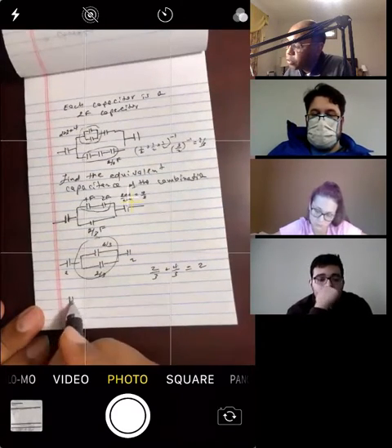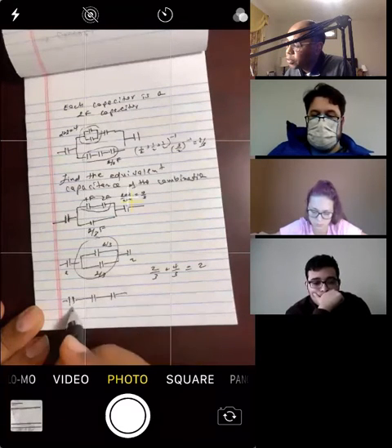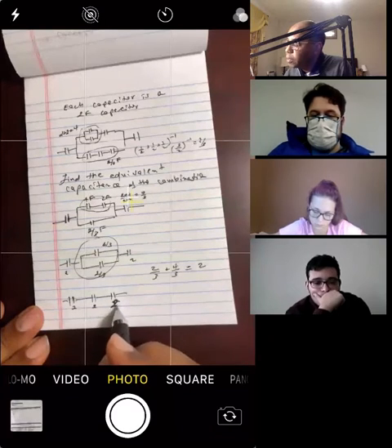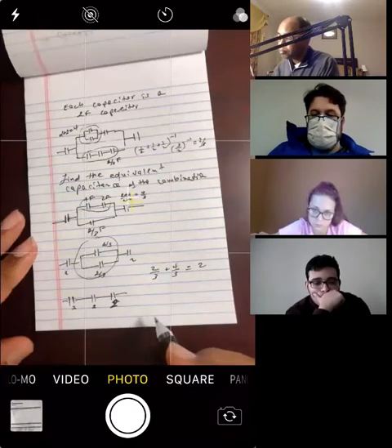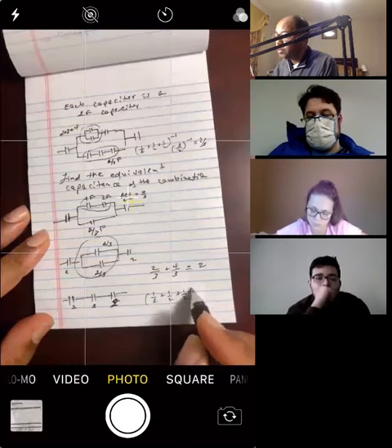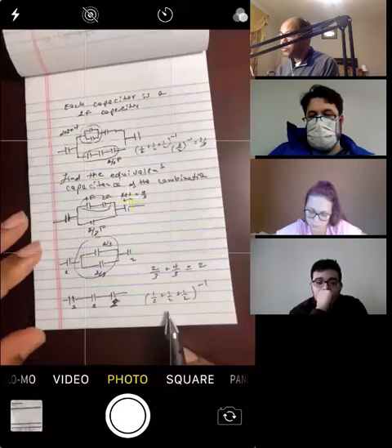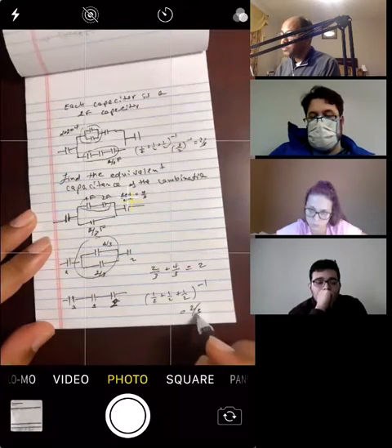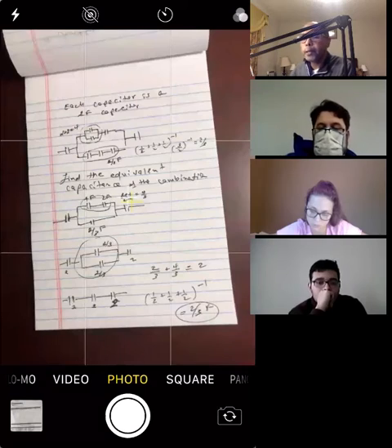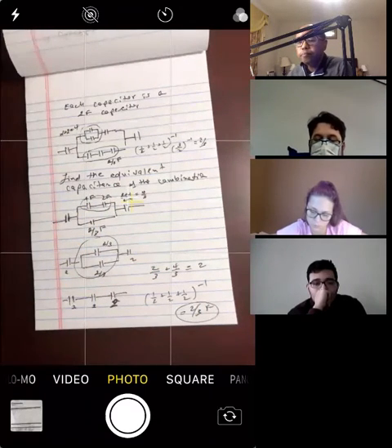I've got a 2 over here. I've got a 2 over here. I've got a 2 over here. Okay. And they're in series and series over here. Okay. And that's going to be, you take the inverses and then the power of -1. Okay. That is 3/2, and you get 2/3. Okay. So the equivalent capacitance of all this combination is just this one. Okay. If you replace this entire combination with this one, nothing will change. All right.